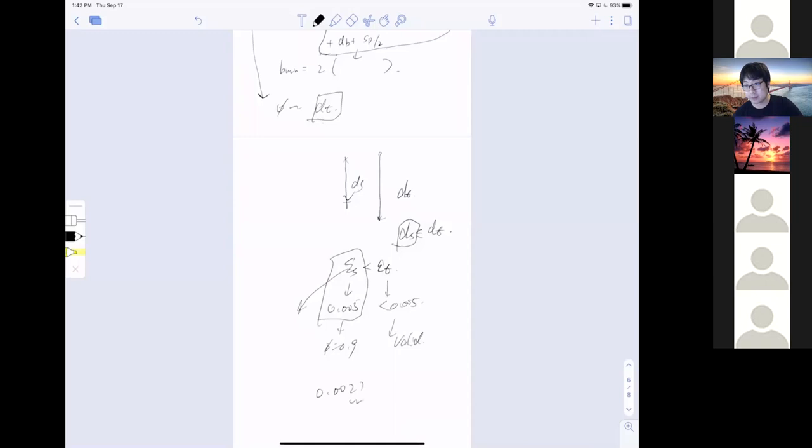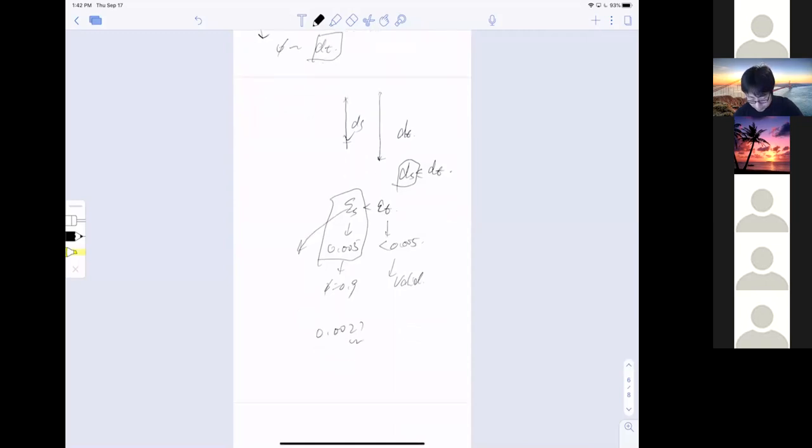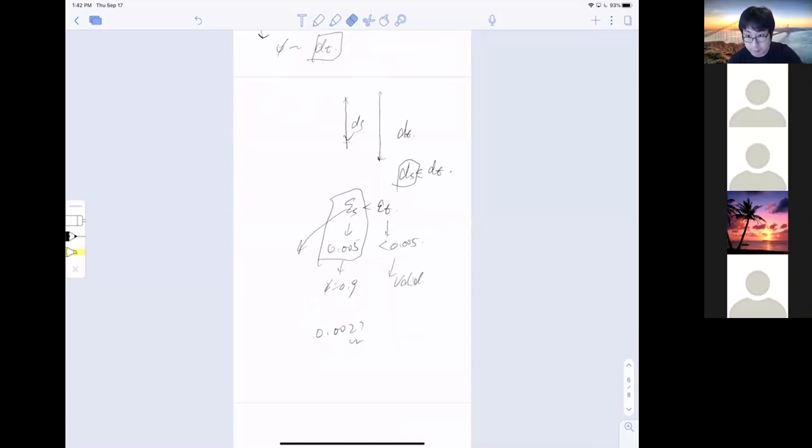Okay, because I found one to be 0.00448, and I used 3 digits. I saw you do that and tried to follow, and I found it to be less than 0.005, so I determined it to be in transition, and phi you have to find using the equation. But you quickly find out that if it sits right on the border, it doesn't matter. You plug in the transition equation and you get something close to 0.9 anyway. Gotcha, and that's exactly what happened.